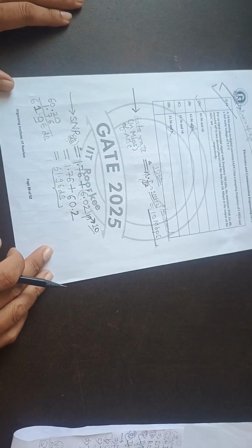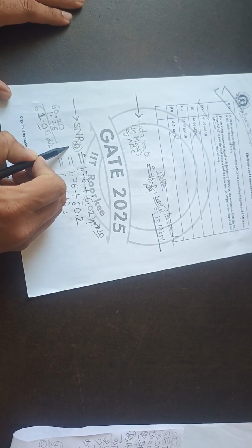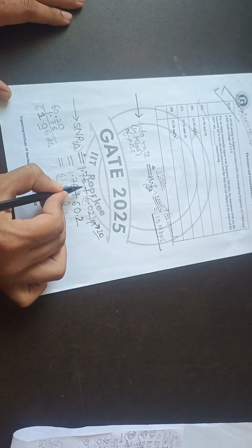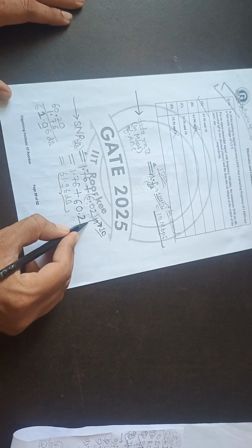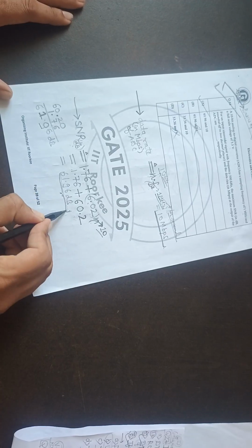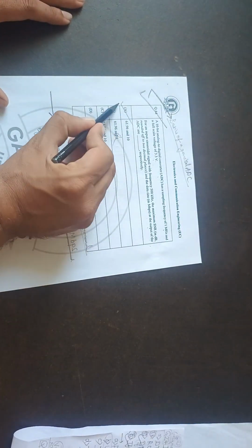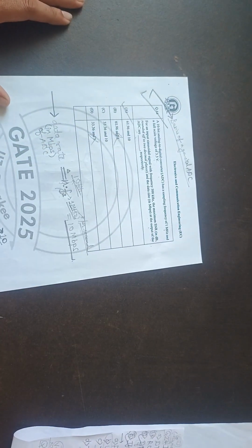The second thing we need to find out is the signal to noise ratio in dB. For a general ADC, it is 1.76 plus 6.02 times n, where n is the number of bits. Simply putting it in, we get 61.96 dB. So 61.96 and 10 is the correct answer.